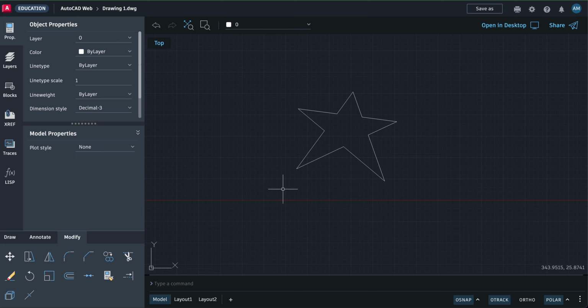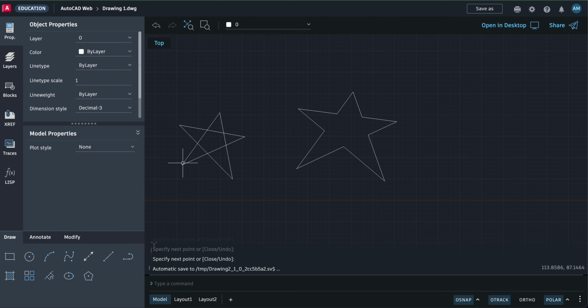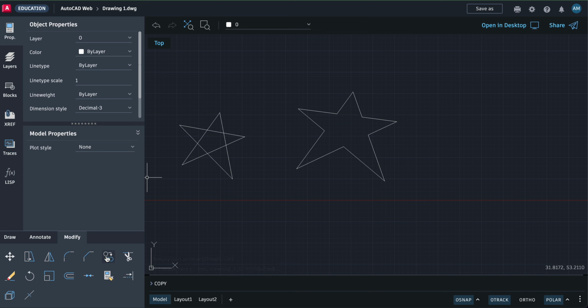So we just learned different commands. First, we learned to draw lines: line, pick, pick, pick, pick, pick, and then go back here, press enter. We learned to create copies, and we can select by making a box from the left to the right. We learned that pressing enter is like stopping a sequence. So I'm stopping the select, and then I'm going to hold it here and make copies. Press enter. We also learned about the erase tool by clicking the erase icon, and then we can erase one object at a time and then press enter.